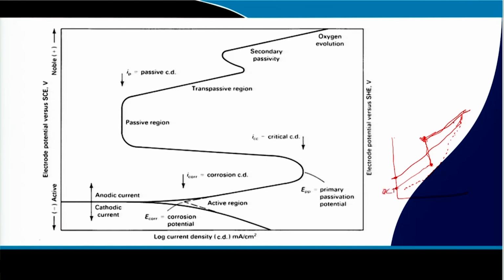Or, if the critical potential for pit propagation is much more active than the pitting potential or open circuit potential, propagation is always there. This kind of quantitative information you can always get from the critical potential for pit formation or pit propagation.